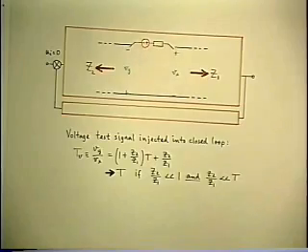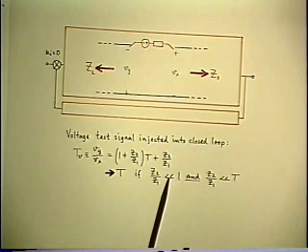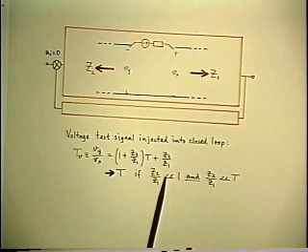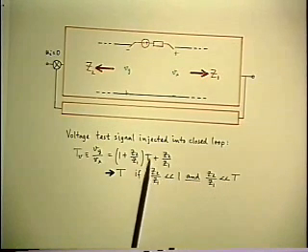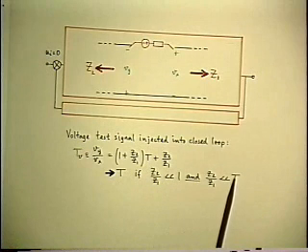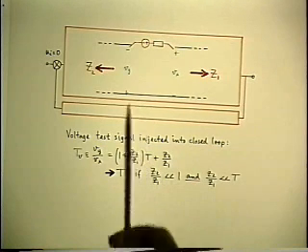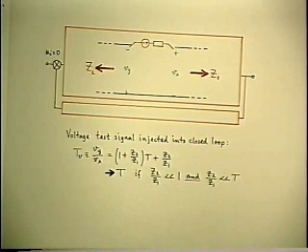At low frequencies, the loop gain is large. So the first inequality is the most stringent one. But when you're measuring loop gain beyond crossover, T now becomes less than 1, and the second inequality becomes the important one. So you have to worry about both of them at different parts of the frequency range.